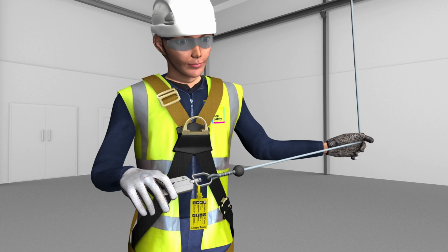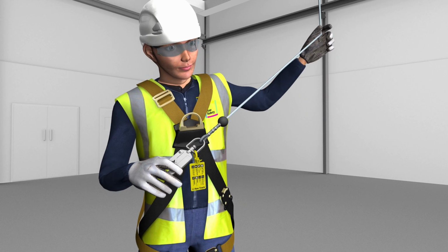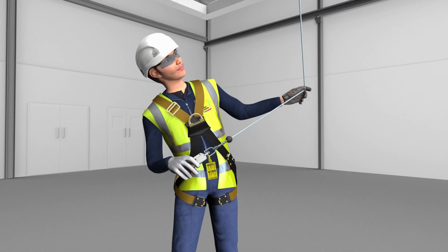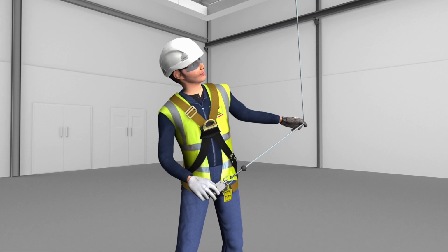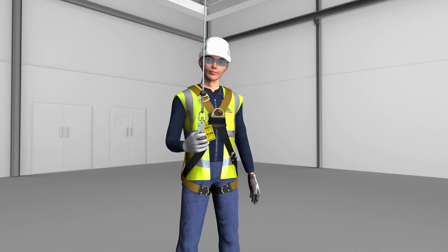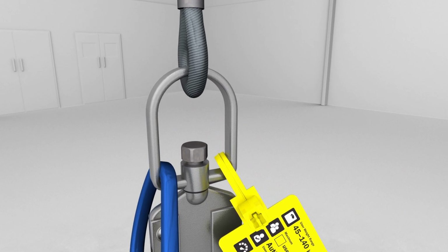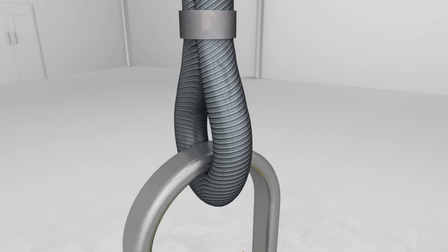Inspect the spring tension by pulling the lifeline out fully and allowing it to retract fully. Ensure the retracting function is operating smoothly and fully prior to checking the lock-up function of the brake mechanism. Retract the cable or webbing fully and inspect it for damage. Carefully inspect the connector, which could be a snap hook or a carabiner, for damage, functionality, and markings.